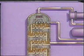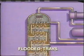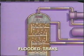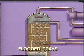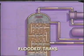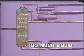There may be several different reasons for this, so an operator must develop troubleshooting skills to identify these types of problems. One abnormal operating situation is flooded trays. When a group of trays in a distillation column become completely filled with liquid, the tower is said to be flooded. Too much liquid flowing down the tower can result in flooding.